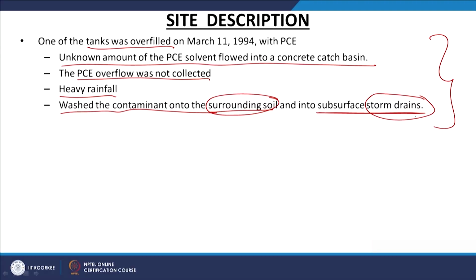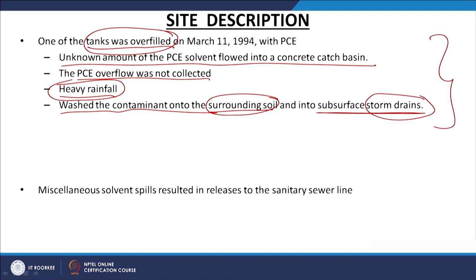Again, we are going to look at those aspects, right. One, as we can see, is that soil is contaminated, and again, as hydrophobic compounds, we looked at it in the context of pump and treat and so on. Pumping them out and treating is not feasible because the compound is adsorbed on soil, which acts as a reservoir of this particular compound, right. So, we know that just pumping and treating it out is not feasible. Again, one particular aspect was the tanks being overfilled and then spill, and then heavy rainfall leading to relevant contamination, right. So, let us move on.